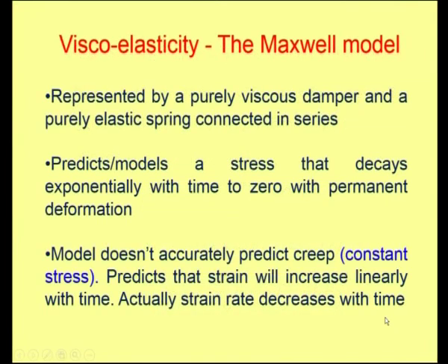So, to summarize the Maxwell model, it is represented by a purely viscous damper and a purely elastic spring connected in series. This model predicts stress that decays exponentially with time to 0, with permanent deformation. However, this model cannot accurately predict creep, that is, when the stress is kept constant, the model fails.